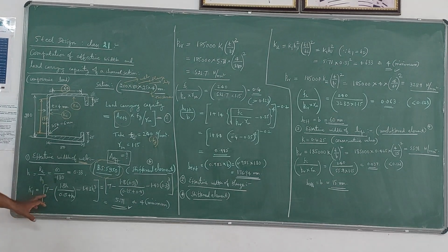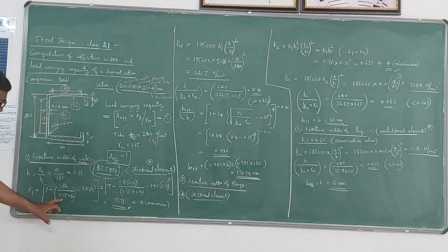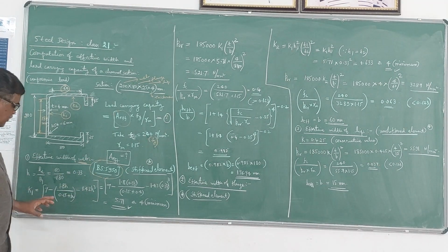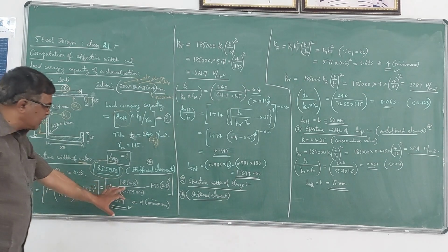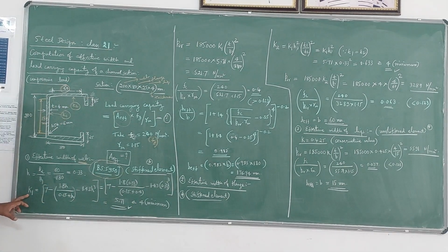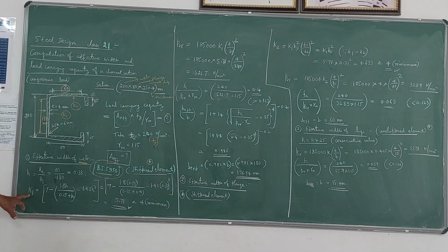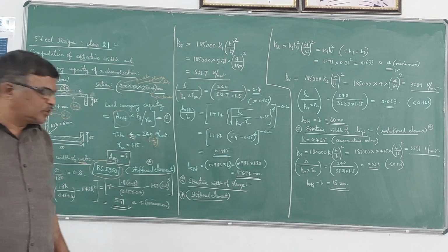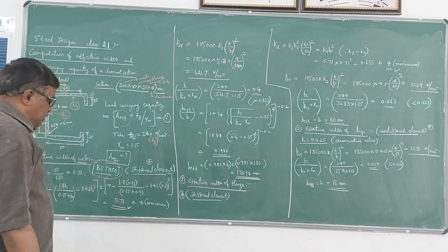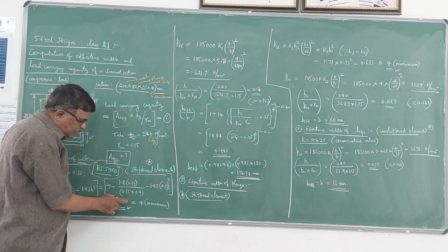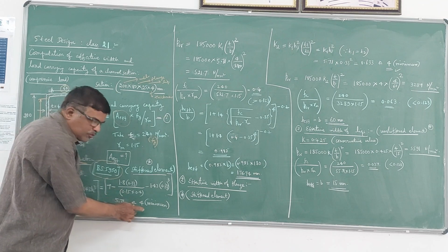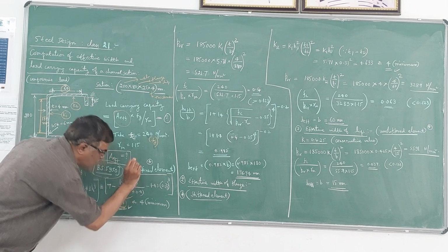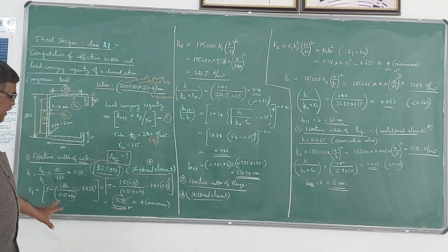So here K1 is 7 minus 1.8 h divided by 0.15 plus h minus 1.43 h cube. Now if you substitute the value of h as 0.33 and simplify, you get the buckling coefficient value for the web as K1 as 5.71. As per the code, a minimum value of 4 should be there. That means if the value is less than 4, you have to take 4, but it is greater than 4, therefore we have to consider this value 5.71 as the value of K1.